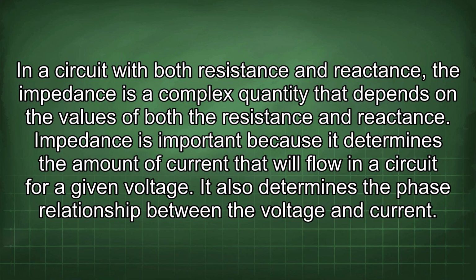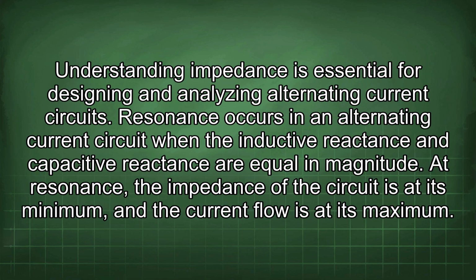Impedance is important because it determines the amount of current that will flow in a circuit for a given voltage. It also determines the phase relationship between the voltage and current. Understanding impedance is essential for designing and analyzing alternating current circuits.